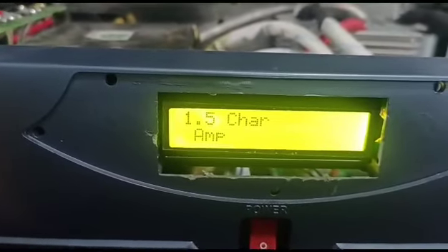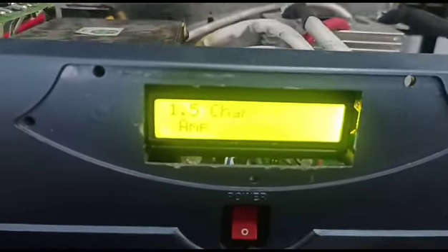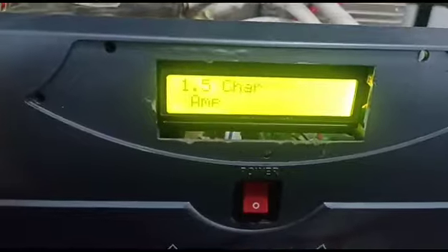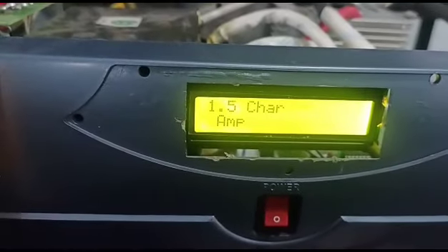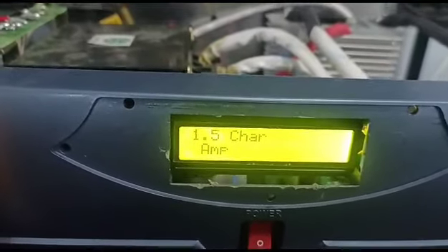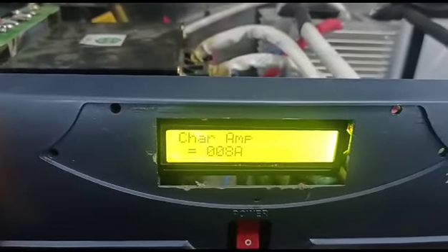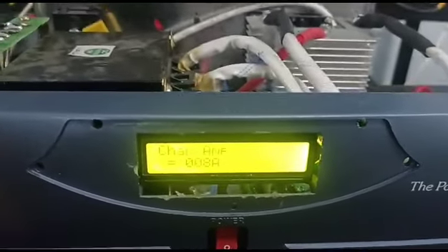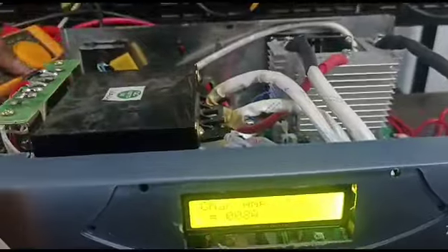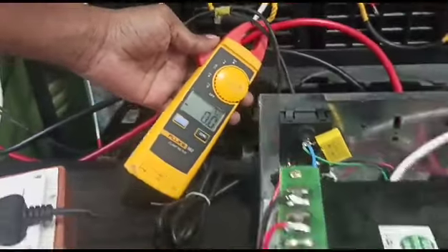Then go to the next option, charge amps. This option you have to set with a clamp meter only. Without a clamp meter you cannot do this setting. Charge amps. You press the enter button and you keep your clamp meter on the positive cable of the battery. Then you have to